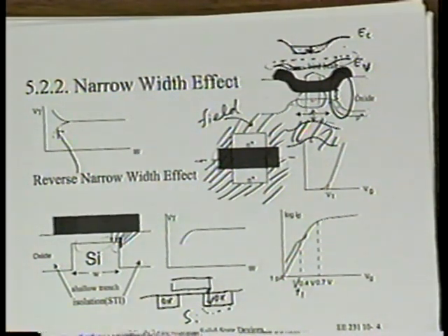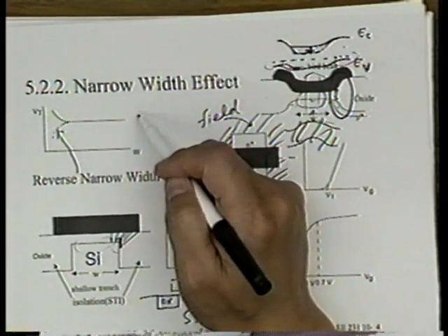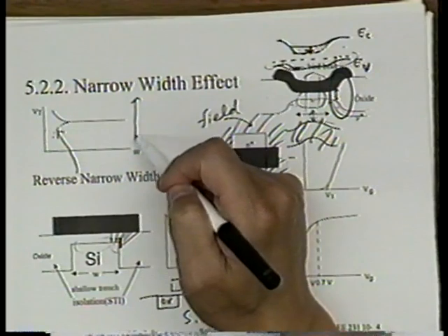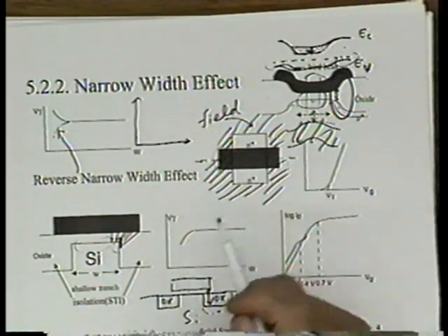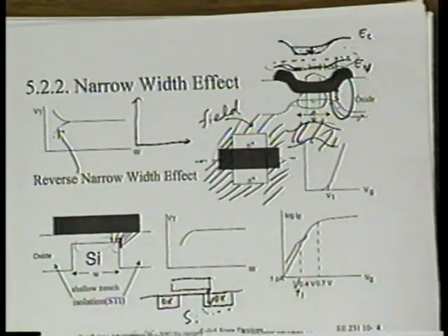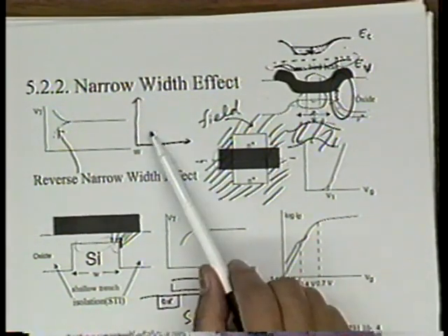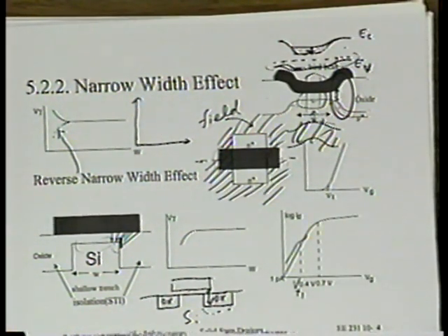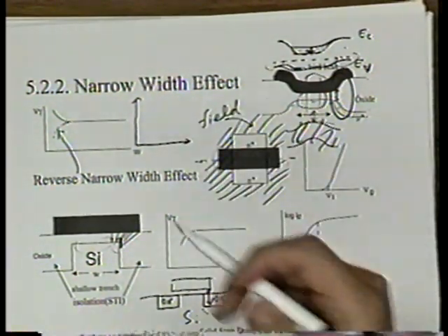So if this is the case for the trench isolation, why is that not the case for the LOCOS? Very good point. All right, I will answer the question instead of phrasing it. I'll first answer in a straightforward manner, then maybe I'll bring up something more subtle. The question is, suppose there's a kink when there are two regions, low VT region and high VT region. You can see two regions in the IV curve. Why don't we see two regions in this case, where we also have a high VT and low VT region?